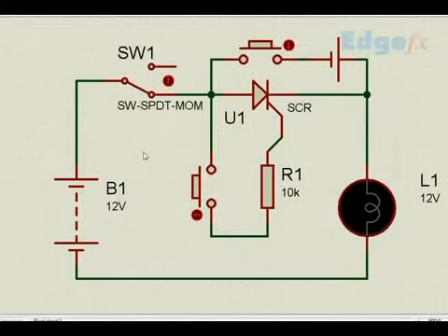In the DC part, what we see is we have taken a 12-volt battery, a switch, a push button switch here, another push button switch here, and a gate arrangement, and a load connected in series with the SCR, anode cathode. This is a load connected. All of us know that a silicon control rectifier, once triggered, that means once the current flows through the gate to the cathode, this is cathode, this is anode, okay?